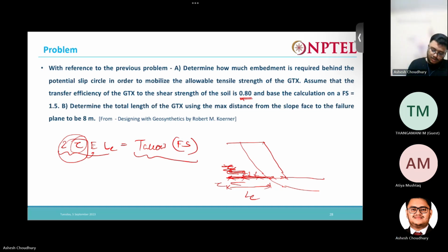All right. So now, to calculate, it is 2. So what will be tau? Tau will be nothing but the shear strength. Here, what will be contributing? The shear strength is contributed by the cohesion only. So what is the cohesion? 15.